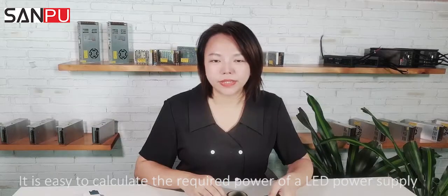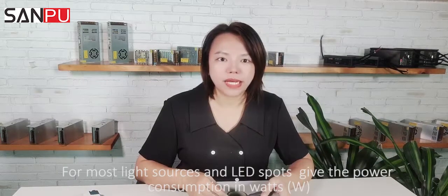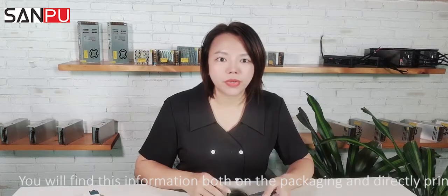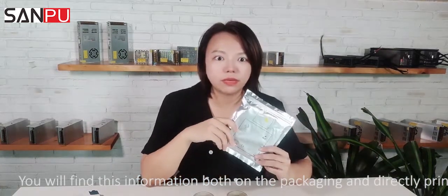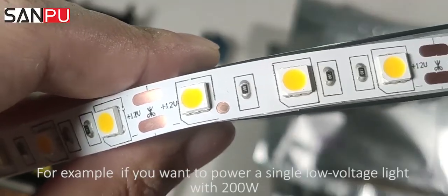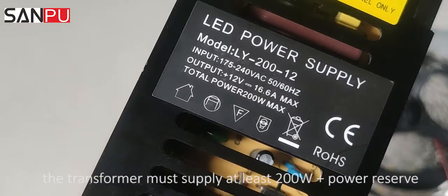It is easy to calculate the required power of an LED power supply. For most light sources and LED strips, the power consumption is given in watts. You will find this information both on the package and directly printed on the lamp. For example, if you want to power a single low voltage light with 200 watts, the transformer must supply at least 200 watts plus a power reserve.